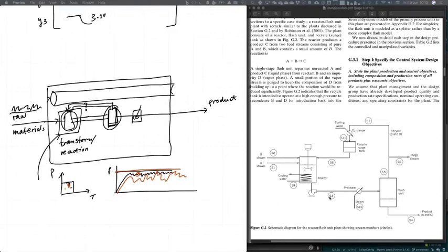hasn't told you that actually it would be great if we had some extra capacity in the sump of that unit. Actually, it would be great if we had a bigger pump so that we could put in an effective control valve. Usually how that works even now is that there's a back and forth. So the process designers design it, and then you get this flow sheet, and then you have to actually add control. You're doing the thing that you're doing now in the control project, right?